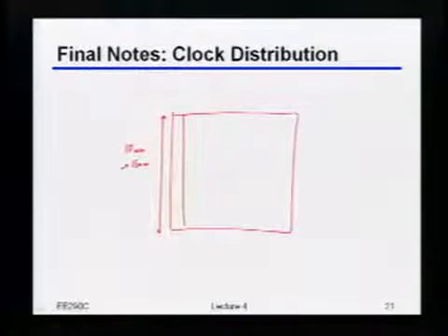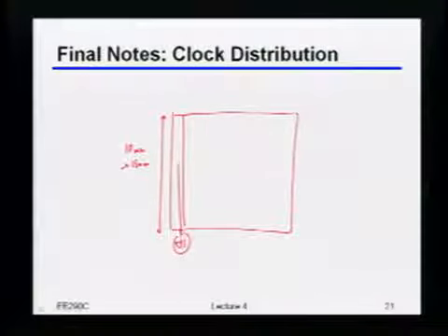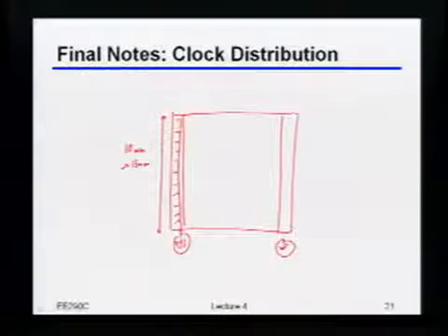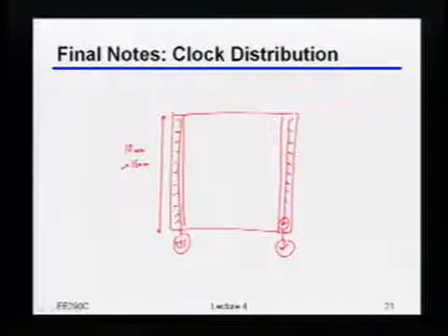If you think about that, I probably don't want 10 different crystal references out on the board for all of my links. So there's probably just one little crystal coming in somewhere, maybe on the bottom side of the chip. That means you either take that reference clock and distribute it out to all of these different links, and then locally have them generate the higher frequency clocks, for example with a PLL. Or maybe you have just one PLL over here in the center and distribute that higher frequency clock out to all of these different links.